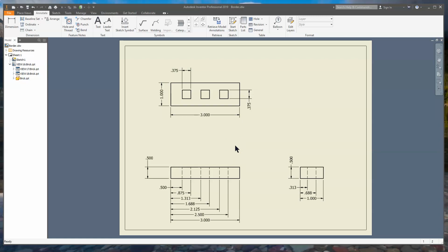Here's an important thing to realize. Do you see that all these dimensions are going out to 3 places? The reason for that is our drawing standards is plus or minus 5/1000ths of an inch. That is 0.005. Whatever my tolerance is, my decimals need to match up to that tolerance. Well, when you start drawing, you're going to find out yours don't match.